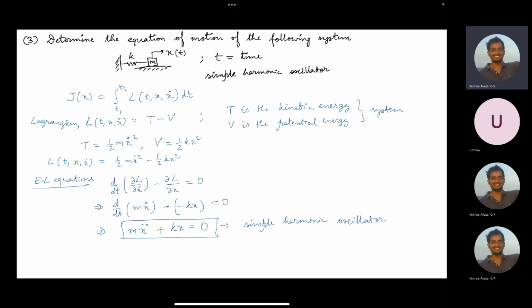The strain energy is the sum of the strain energies in each of the springs. For the first spring, one end is attached to the wall, so the extension is just x1. For the second spring, one end is connected to mass 1, whose displacement is x1, and the other end is connected to another mass whose displacement is x2.